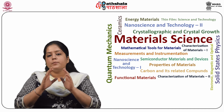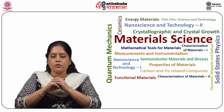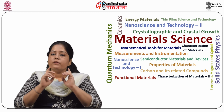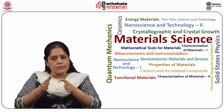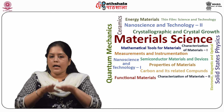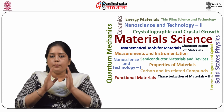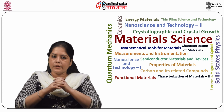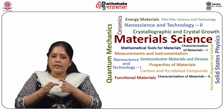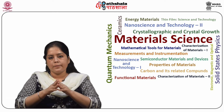Epsilon prime and epsilon double prime, they are the real and the imaginary parts of permittivity. So, when we are determining the figure of merit, the dielectric properties must be measured at a frequency similar to the range in which the pyroelectric device is to be used. This is because the dielectric properties are frequency dependent.